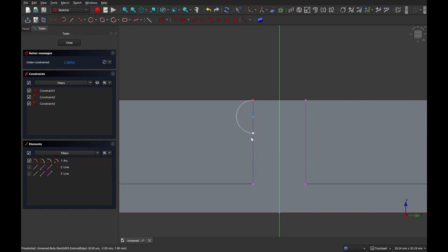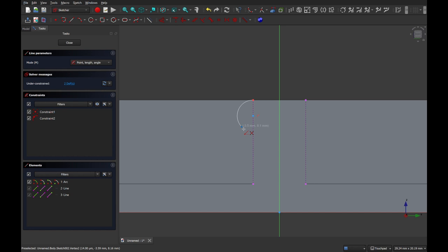Now, for 3D printing, so that we don't need supports, you actually would like to have that at 45 degrees. Now, it won't make much difference, I think, for this print, but let's fix that. So we'll get rid of this constraint there. Let's move this up to about there somewhere, such that you can make it 45. We'll draw a line that now joins there.